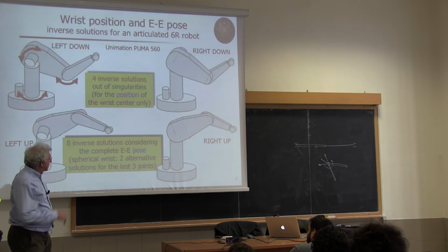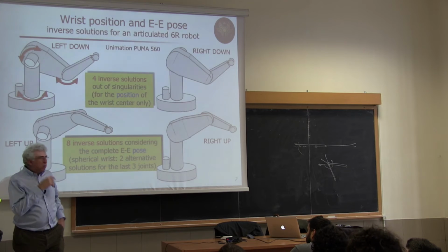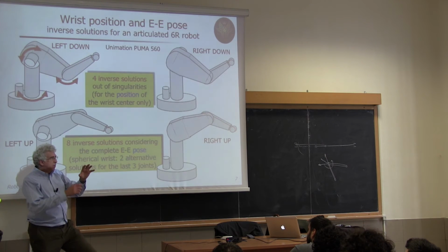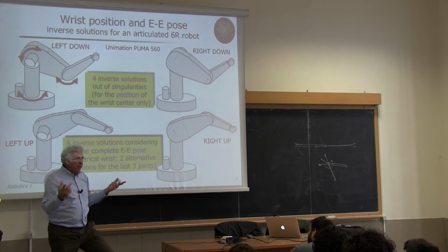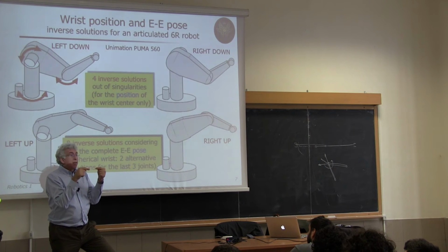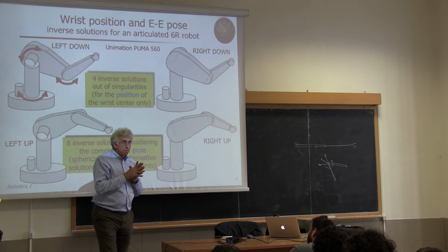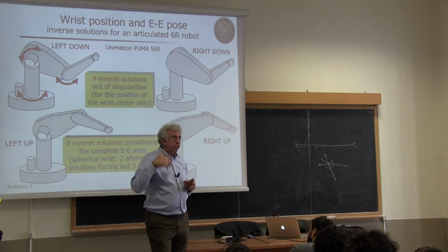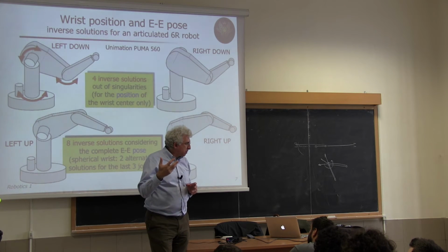So, the point is that, again, suppose that there are no joint limits. Now, forget about the first 3. So I have only the wrist now, which has 3 possible rotations around joint axis 4, joint axis 5, and joint axis 6. And these axes are all incident to the same point because this is a spherical wrist. So the axes always intersect. So these 3 joint variables, theta 4, theta 5, and theta 6, are in fact a sequence of Euler angles.